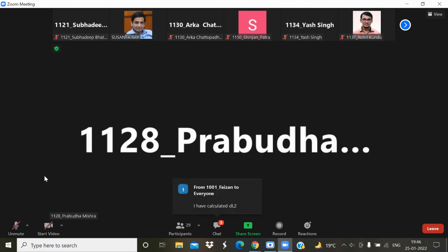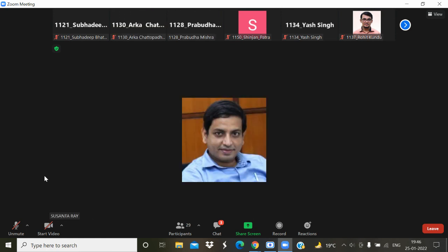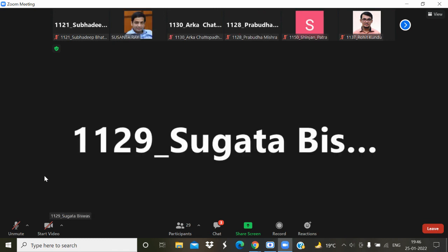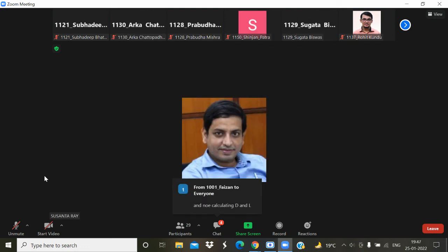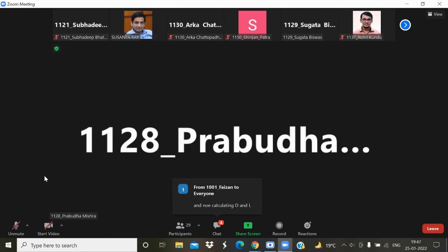Sir, for 100 kilowatt machine, 1000 RPM, my D is coming 398.66 millimeter and L is coming 417.476 millimeter. Okay. Sir, for 110 kilowatt, my D is 384 and L is 402. Okay. What is the L by tau ratio you are generally assuming? Sir, 2, sir. Okay.